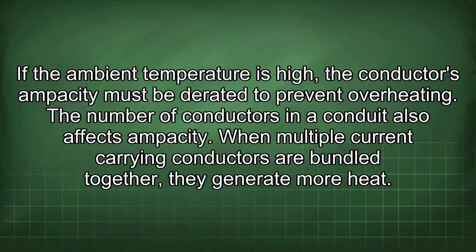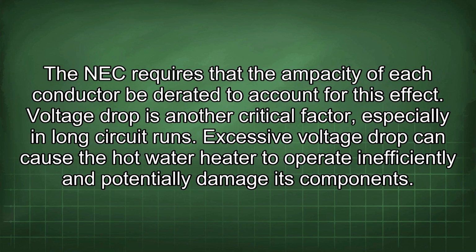The number of conductors in a conduit also affects ampacity. When multiple current-carrying conductors are bundled together, they generate more heat. The NEC requires that the ampacity of each conductor be derated to account for this effect.